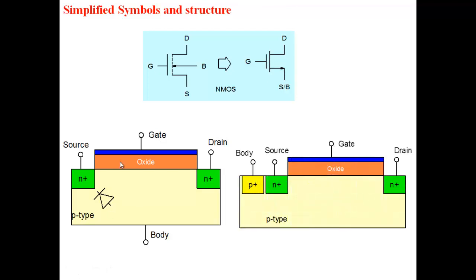And so note that if you look at this particular picture here, again these are simplified schematics. So we have metal, oxide, semiconductor, N plus source, N plus drain here. And to make a contact to the body, I may create a P plus layer here. Note that the body is P type. So I may create a P plus layer here and put a metal here. The reason why, I've said that earlier, we always put P plus, meaning a region which is heavily P type doped, is that metals that you deposit here don't make good contact to a normal N type or a P type semiconductor. Good contact means there's very little voltage drop across it. You have to make a region which is P plus.